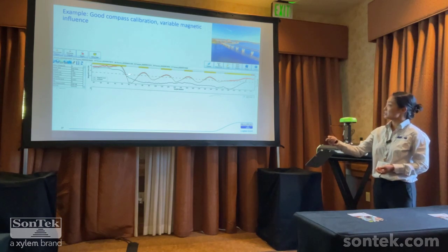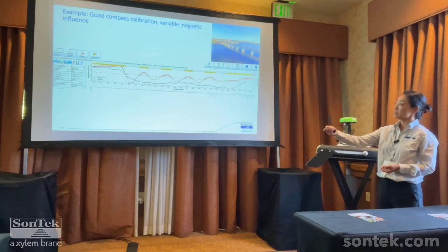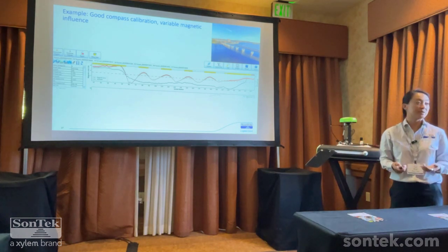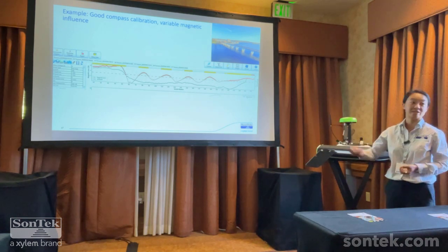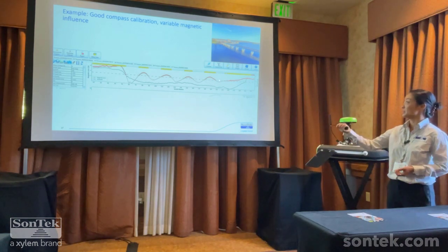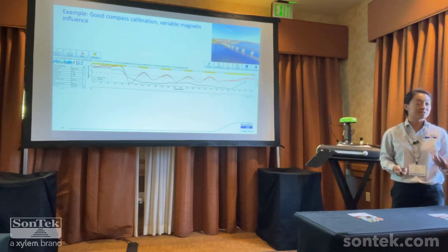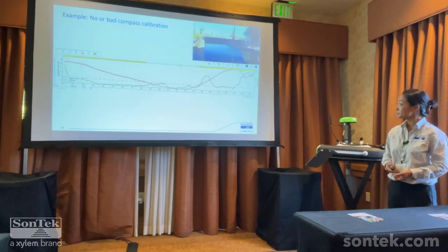And so you see this dotted line here, that's a 3.5% threshold that we use, and we generally say that anything above 3.5% error will start to interfere with your velocity measurements. So it's just something to keep in mind. The software will actually give you some indication when you hit these values. Just make sure to look at your data and make sure that they make sense as you move across your transect.